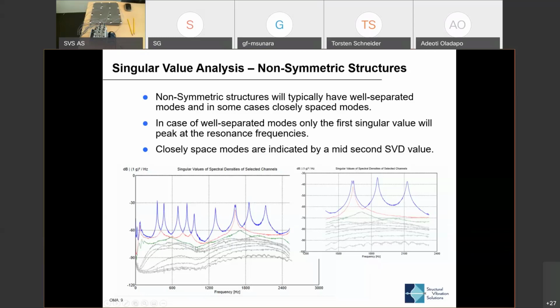So because we have all these lines, we can visualize the way that this mode is actually behaving through the frequency range. This can, of course, only happen if we have the lines. And the lines here only appear when we have multiple excitation points that I'll come back to.